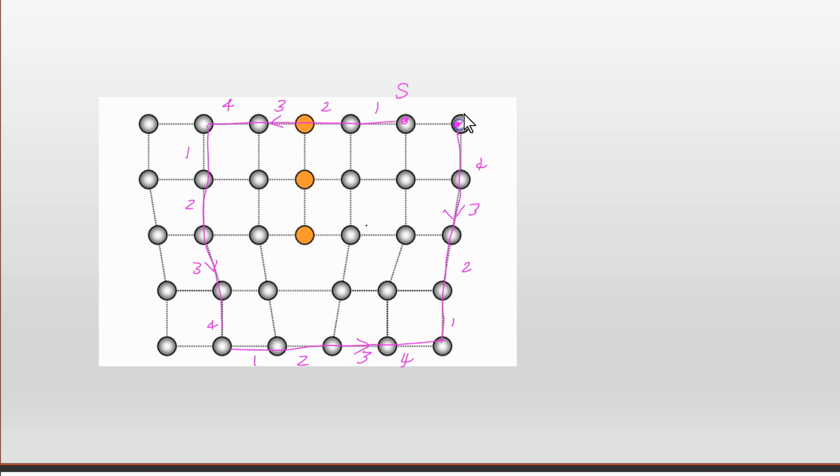Now what I found is that the start and the finish were not the same point. So my Burgers vector goes from the start to the finish. That's my Burgers vector for this dislocation.